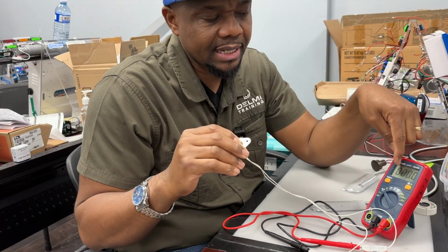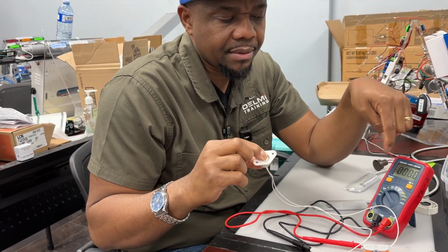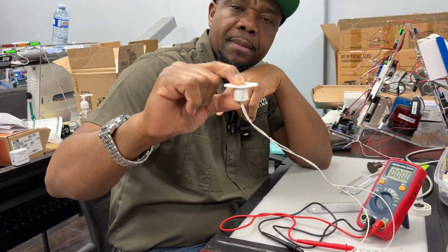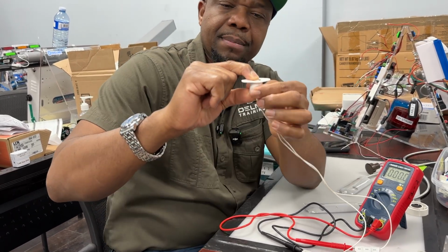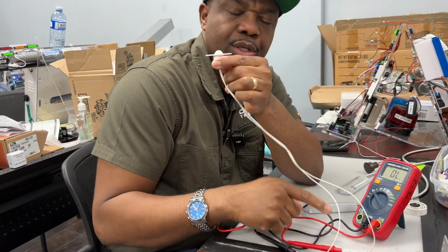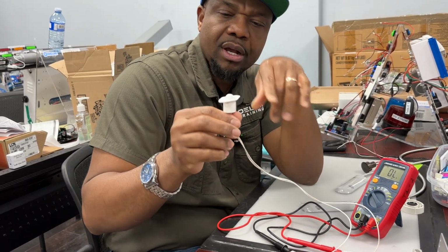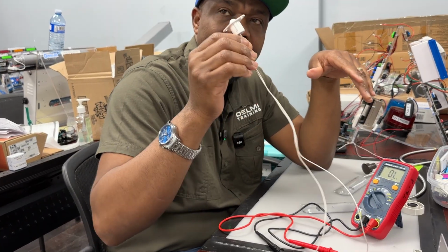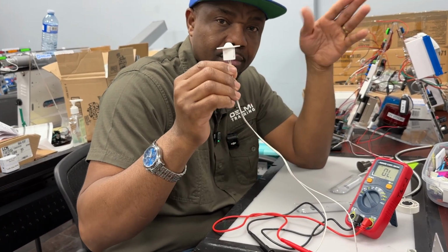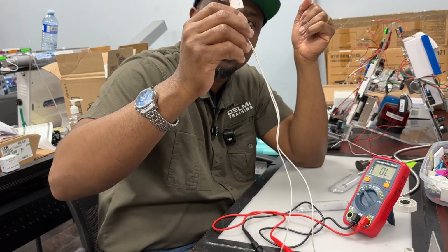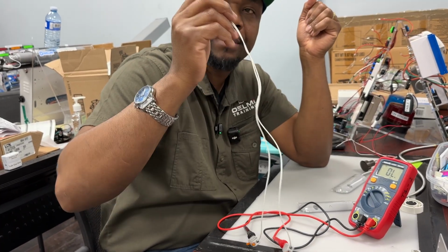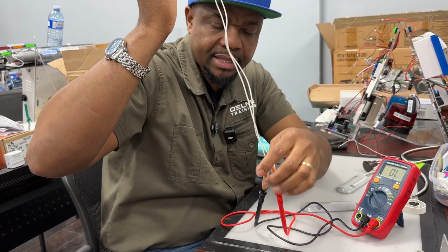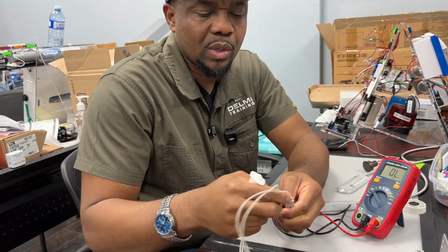By depressing it, I can see on here that there is pretty much no resistance on this entire loop, and that's going to beep. Once I take my finger off, the beep is going to stop. Because this is the default state and there is no beep, this is a normally open switch. All right, so I can conclude that this is a form A switch because it's open by the default state. Now I'm going to grab a next one.